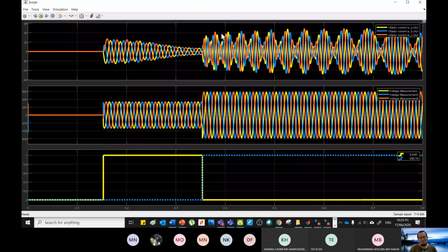It's like the video of the motor starting that I shared with you. Remember, when you start the motor in star, the sound is very slow. After the motor has gained momentum, we switch over to delta, and the motor starts spinning very fast, up to its rated speed. Rated speed means the normal speed. Initially in star, the speed is very low.